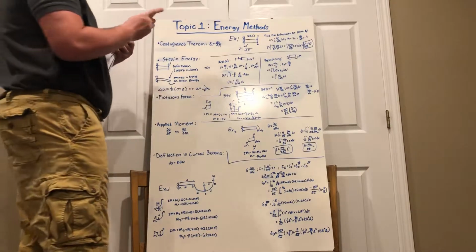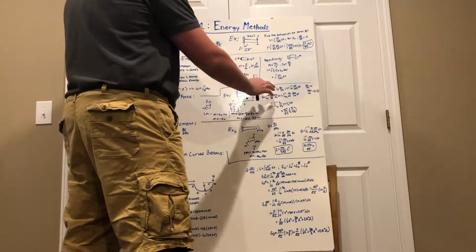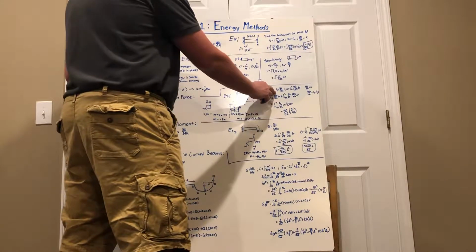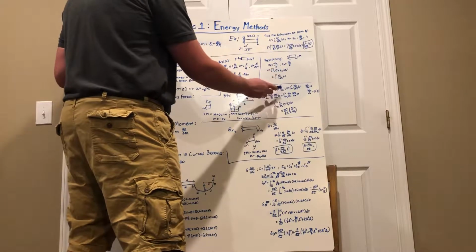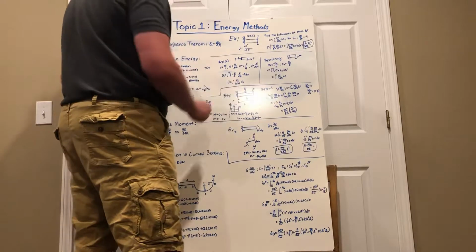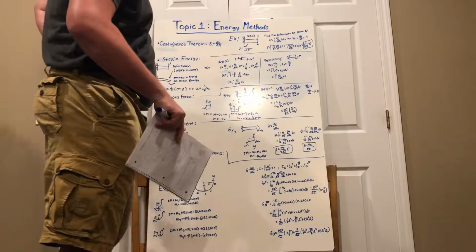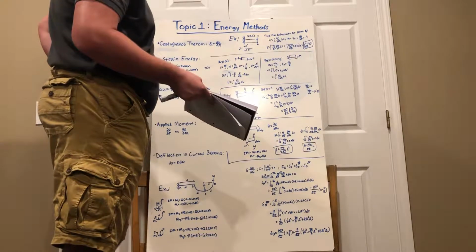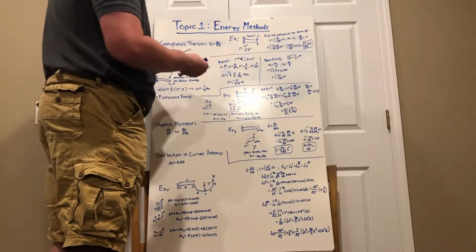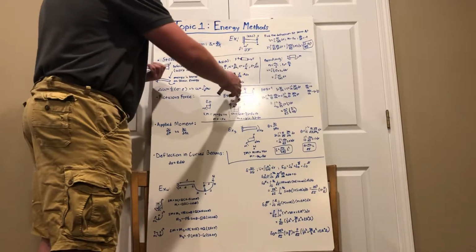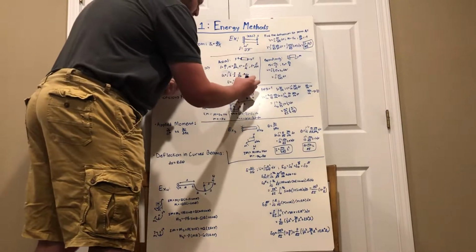Now, with those in mind, we're going to come back over here to our problem. We're going to remember our deformation equation. It's going to be the partial derivative of this strain energy with respect to, this time, the imaginary force. Why are we doing it with respect to the imaginary force? Well, because it makes the math a little easier, and because we have to take care of this fictitious force and not forget that it's doing this. Remember, this fictitious force is going to have a magnitude of 0.